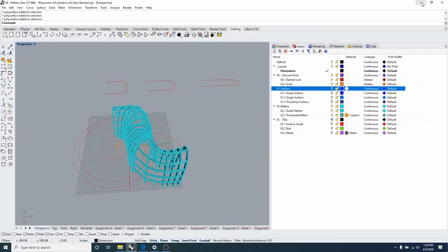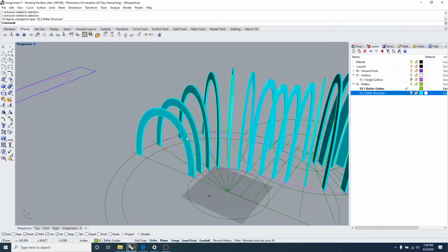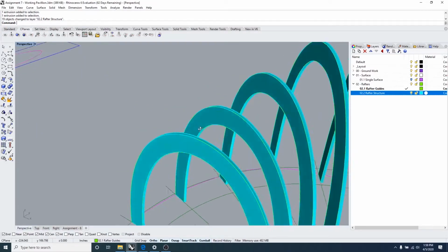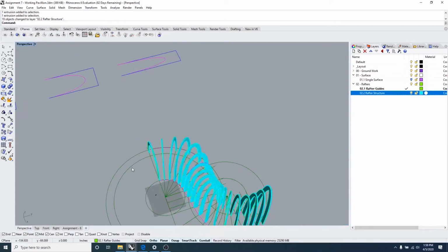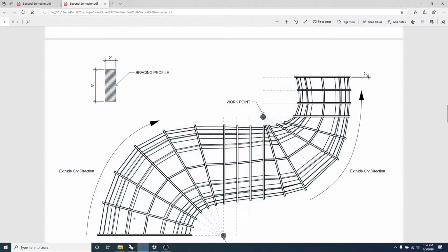So now that we talked about that, how do we go about creating those? We talked about the rafters, how to create those, but we haven't talked about how to do the bracing between one another one. And the way we do that is by, one, creating a profile, which is the profile that we were just talking about, which is the 6x2, a 6-inch by 2-inch.